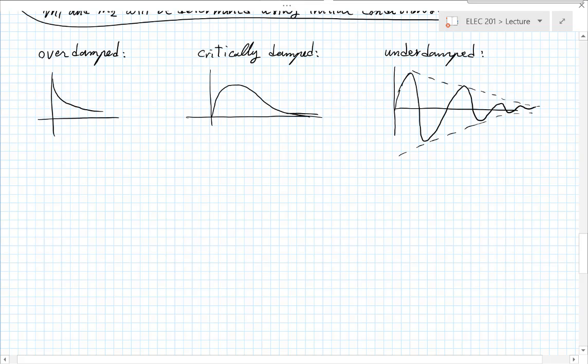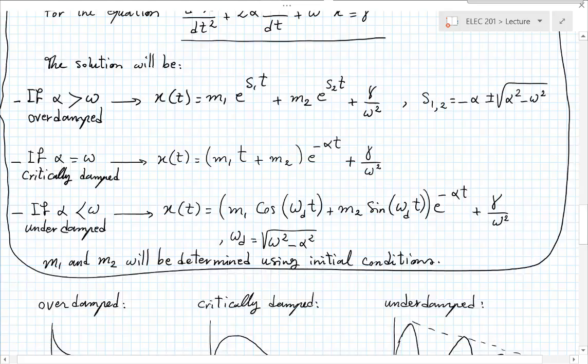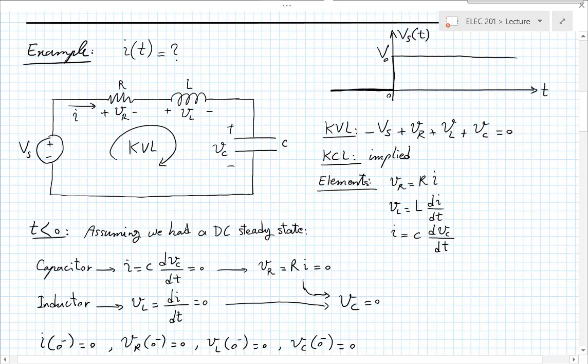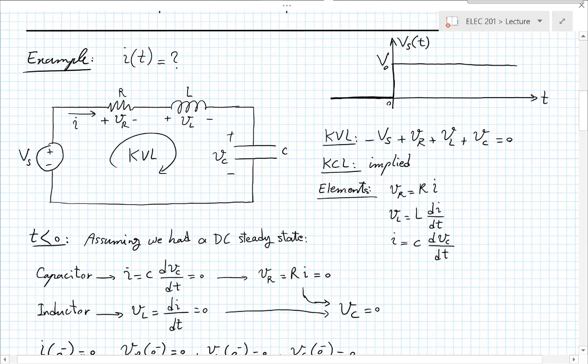Are there specific things that we can look for to identify that a circuit is second order? Now let's look at how this circuit became second order. It was really the consequence of the fact that the voltage of the inductor was proportional to the derivative of the current, and the voltage of the capacitor was proportional to the integral of the same current. So there were 2 orders difference there. This happens very often when you have more than one element that has time dependence, capacitance or inductance. But you have to be careful not to generalize that too much.